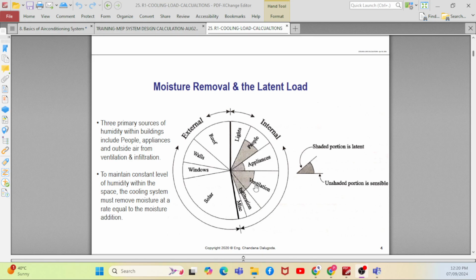So this ventilation, what are they considering it as? It is from external to internal only, right? Maybe it is from external to internal, and inside it is affecting the load. You are bringing ventilation air from outside to inside, so it is affecting the space. That is the way they may consider it as internal. Just one doubt: considering a simple FAHU, it will take out the air from the cool space and take the extract air back. Could this be the reason it's considered in the internal part? Yes, that is because it is affecting the internal space. So that is the reason they have considered it as an internal portion.